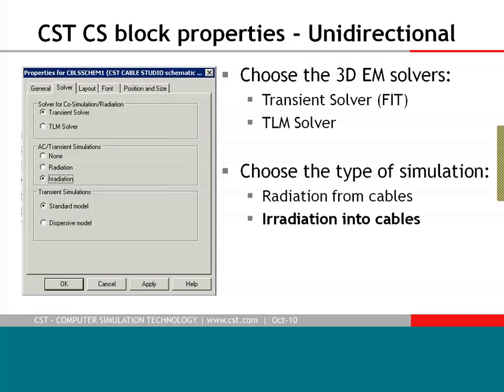So here I will go fast through the, let's say, features, but I hope you can easily request, or have your contact partner at CST, to test the 2011 release, which supports all these new features. So you can decide which kind of solvers you want to use. You can even consider the TLM. I use the transient solver for that. And the type of simulation, radiation from cables or irradiation into cables. So I choose the second one, since we decided to have just a unidirectional coupling.